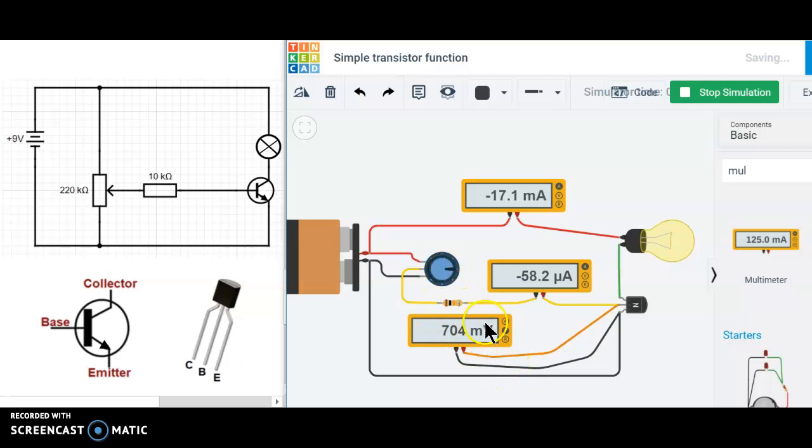All right, so the bottom one is the voltage between the base and emitter. You find that this voltage changed just a little bit in this whole control circuit. So I start from here. Initially it's nothing because the voltage here is 0, so that's why you measure the base to emitter as 0.